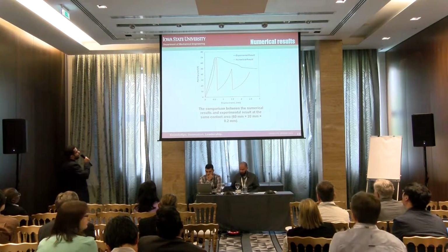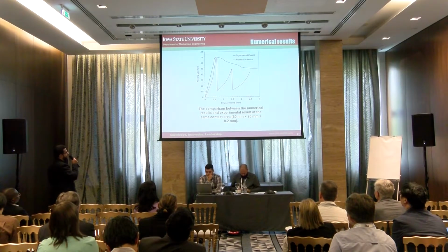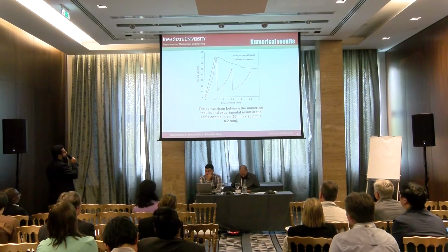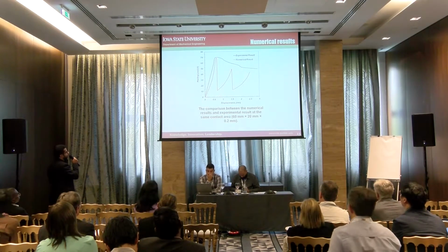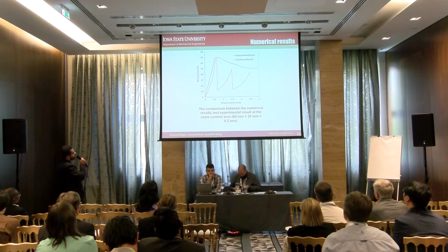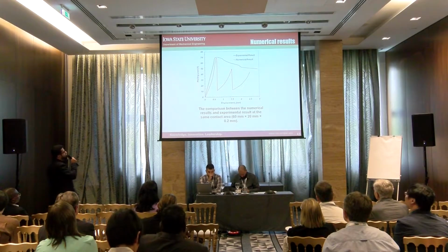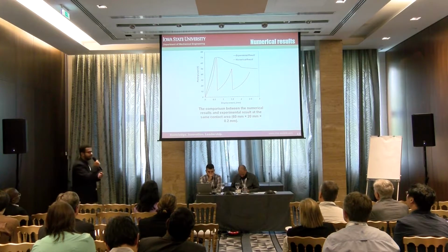So for the results, comparing the numerical and the experimental results, we can see that for the first stage, until the max point, we have a linear agreement until we get the maximum. Then the crack is initiated. We have a very big drop, or we can see a sawtooth, which can be a phenomenon for this kind of composite. Until this stage, for the maximum load, we have a very good agreement that we can use for this kind of study.